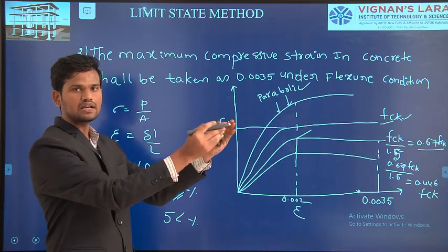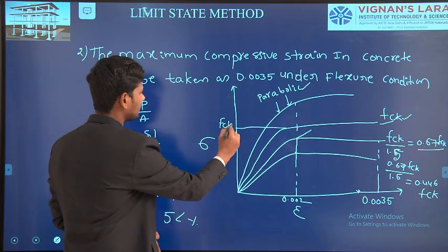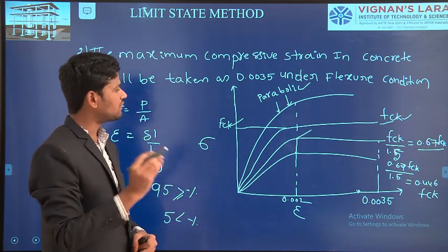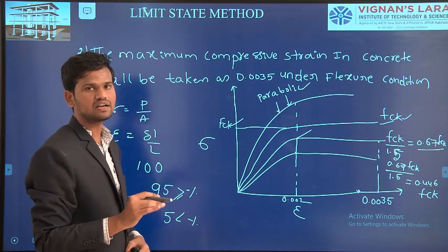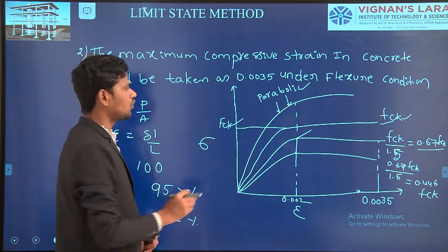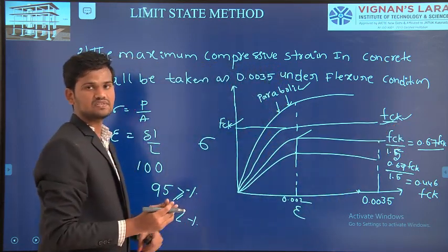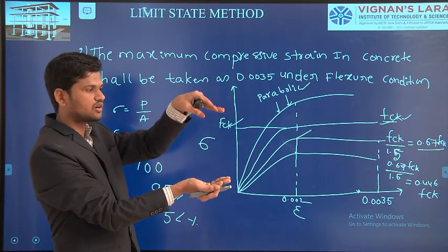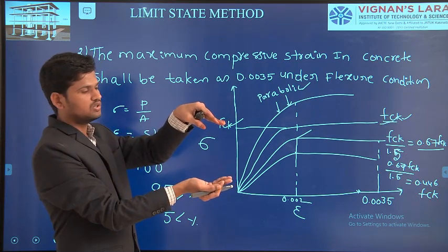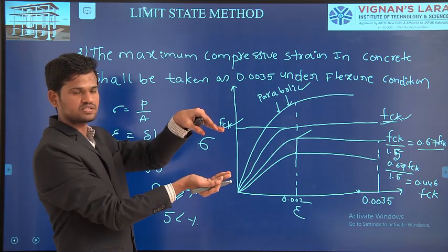While preparing concrete for testing a cube, it will give the exact strength, fck. But while making this concrete in the actual structural member, it does not give the exact value. Why? Because in laboratory testing on the compression testing machine, for characteristic strength fck, the cube is placed between steel plates at the top and bottom. Due to this, the concrete gives more strength.